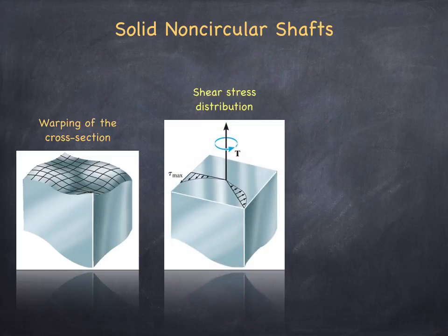In the circular shaft, if you recall, the cross-sectional shear stresses were 0 at the centroid, and they became a maximum at the perimeter points. But at the corners of a non-circular shaft, at those edges, the shear stresses must be 0 due to balance of angular momentum. This is quite unlike the distribution we encountered for the circular shaft.